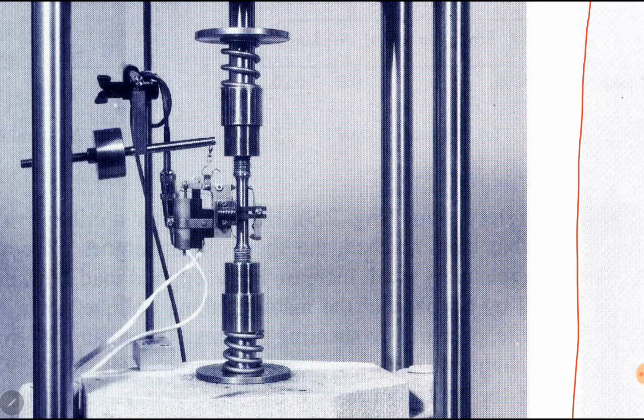Okay, now we know that B is moving upward and D is coming downward, so we can draw. BDE is a rigid member, so it will not deform, but it can rotate. So it will remain straight even after rotation. B has moved upward by an amount equal to delta B, which is known. D has moved downward by an amount equal to delta D, which is known. E will come down to point E dash, and the distance EE dash, which is delta E, is still unknown.